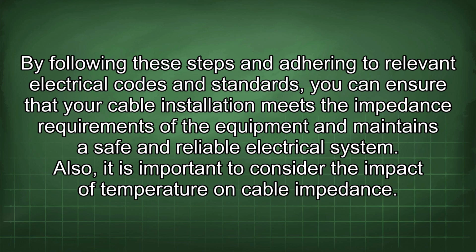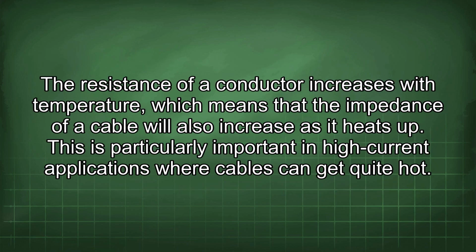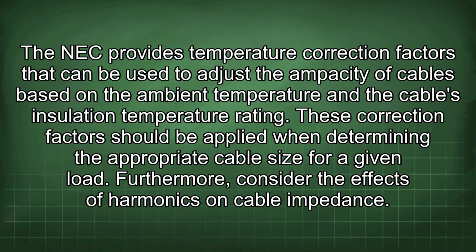Also, it is important to consider the impact of temperature on cable impedance. The resistance of a conductor increases with temperature, which means that the impedance of a cable will also increase as it heats up. This is particularly important in high current applications where cables can get quite hot. The NEC provides temperature correction factors that can be used to adjust the ampacity of cables based on the ambient temperature and the cable's insulation temperature rating. These correction factors should be applied when determining the appropriate cable size for a given load.